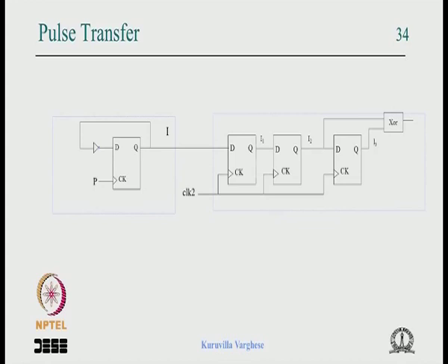And if there is a pulse, it can be stretched to be neatly detected by the state machine. In the first circuit we have shown, it is stretching it by an integral number of clock cycles, but this is a better scheme. We are not even stretching it, we are toggling it. It is an extreme case of stretching it.